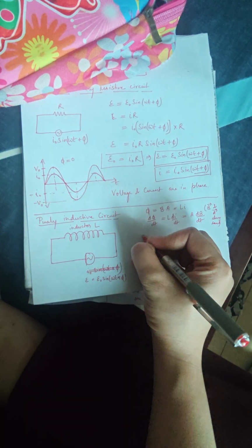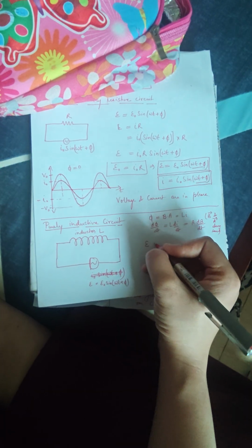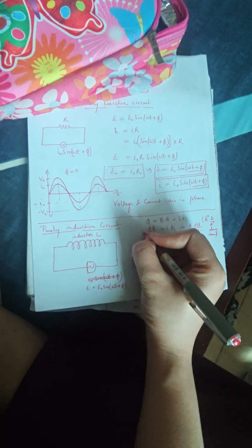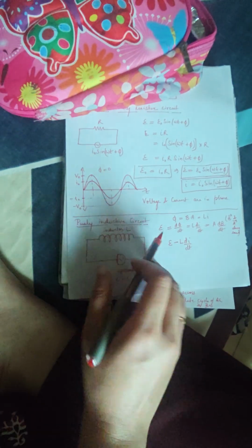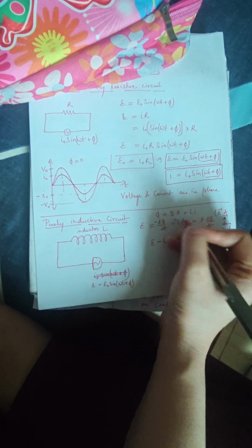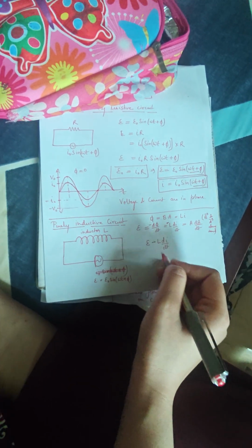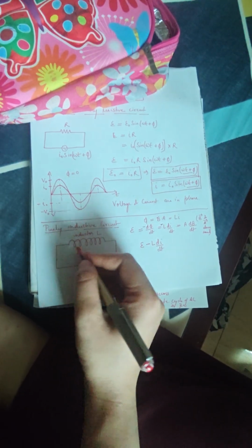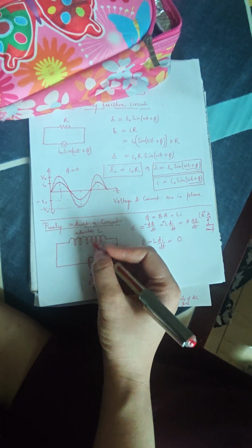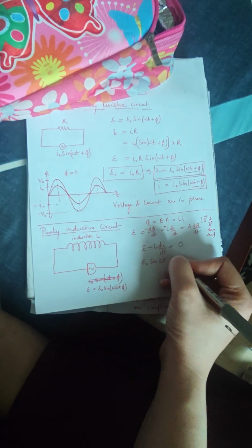So you can see that I'll apply the EMF E like this. I'm just applying Kirchhoff law here, and the voltage drop across it will be L di by dt. If you remember the last chapter, Lenz's law, E is equal to minus d phi by dt. Then you will put it here, then it will turn out to be plus. Yes, so this is how it is. So E minus L di by dt, the EMF generated across the inductor. This is what I have given to the circuit, and it is coming out to be 0 because these are the only two components in the circuit. So I'll put E naught sin omega t here equal to L di by dt.